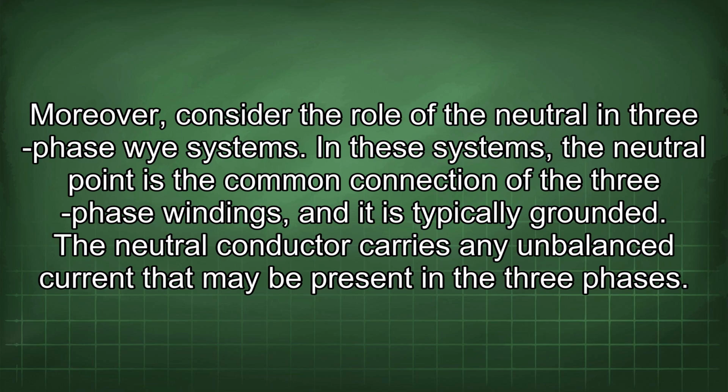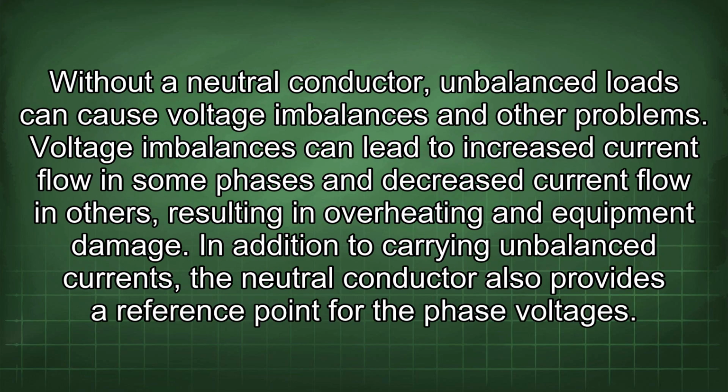Moreover, consider the role of the neutral in three-phase Y systems. In these systems, the neutral point is the common connection of the three-phase windings, and it is typically grounded. The neutral conductor carries any unbalanced current that may be present in the three phases. Without a neutral conductor, unbalanced loads can cause voltage imbalances and other problems. Voltage imbalances can lead to increased current flow in some phases and decreased current flow in others, resulting in overheating and equipment damage.